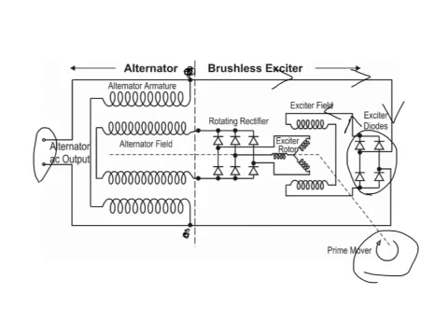In order for us to start to build up a voltage over here at our output, what had to happen first of all is there had to be residual magnetism, due to a small, fairly weak north and south pole existing on the exciter field. If there is no residual magnetism, clearly we're not going to build up, or there's a chance we won't build up. So we're assuming here that we have some residual magnetism in that north and south pole in the exciter field, which you'll notice is located in the stator.